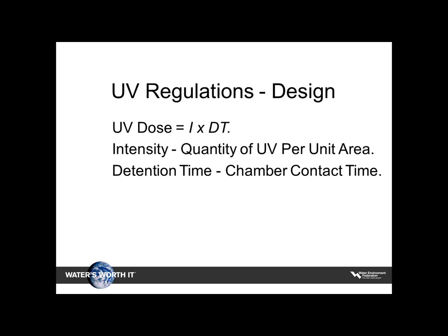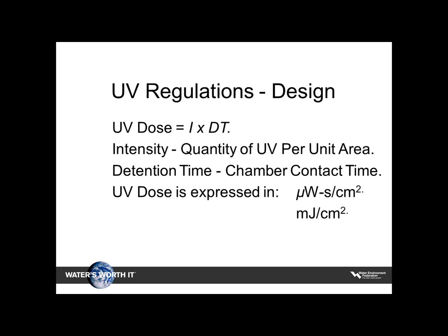One of the big things any regulator is going to want to look at, some of the things they're going to be concerned with, is what the intensity is and obviously what the detention time is. So I guess it's the dose. Now they may think they're interchangeable. Again, dose may be expressed in microwatt-seconds or millijoules. And some vendors give you both information.